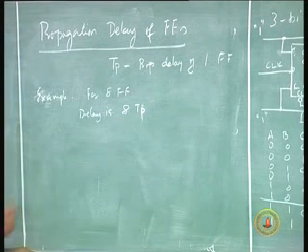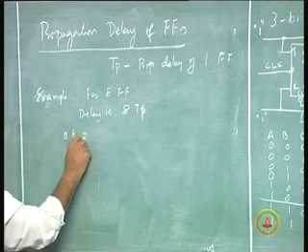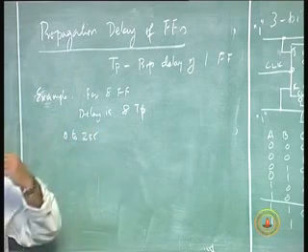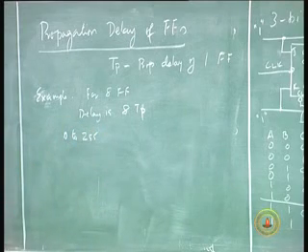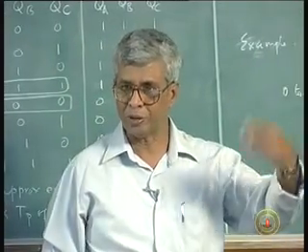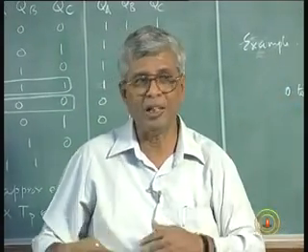256. So for a count from 0 to 255, each count takes 8 Tp to materialize. If I am at 0, after 8 Tp, 1 comes, after 8 Tp, 2 comes, and so forth. Reliably, of course, something can happen faster than that.